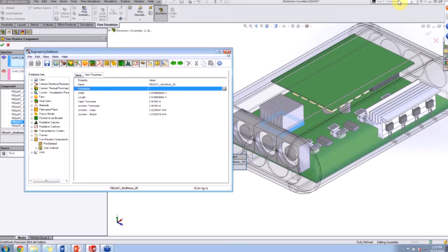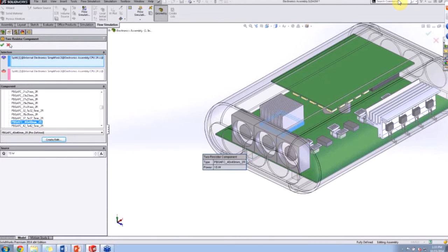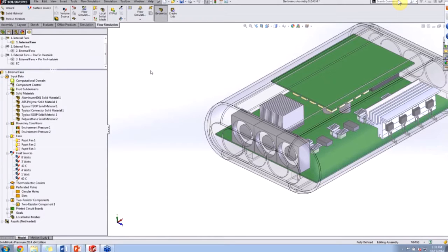We can definitely get away with this with just specifying what that conduction value is for just a basic solid. But again, it's just more accuracy, a little bit more diligent as far as what's actually happening. End result is just to get a more fine detailed result there. Same goes with this printed circuit board. So we can specify some material for our circuit board there, give it some kind of conduction value.